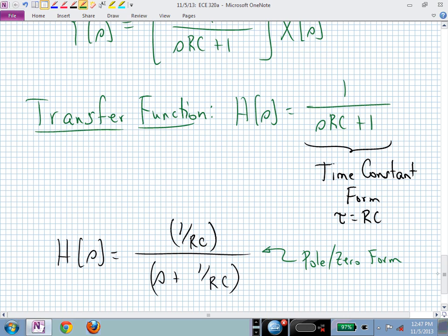So now what is complex in this particular circuit? Now we're letting S be a generalization of our phasor j omega. S can now be a complex number, not just purely imaginary. S is now potentially anywhere in this two-dimensional plane that has the real axis and the imaginary axis. I'm not sure if that's answering your question or not. But this is now our transfer function that we find in terms of our complex frequency variable S.